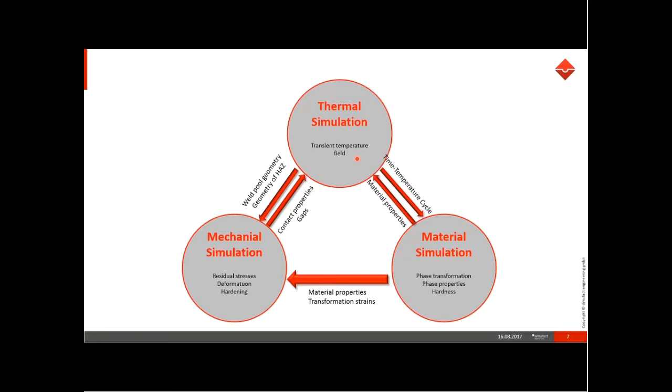So what we have in the end is a coupled thermomechanical welding simulation, and this is what our product Simufact Welding provides. Simufact Welding is not a product where you can sophisticatedly simulate a process zone. You have to rely on these equivalent heat sources in order to get a fully coupled thermomechanical welding simulation, which is also often called structural welding simulation.